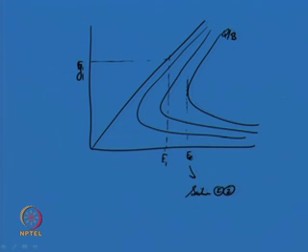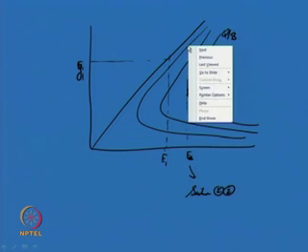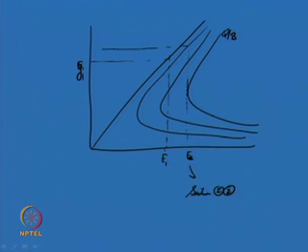So, you have to take that as the minimum specific energy at section 2, extend it and see at which location this portion comes. So, you have to see a new modified specific energy at section 1 arises. This is called E 1 dash.